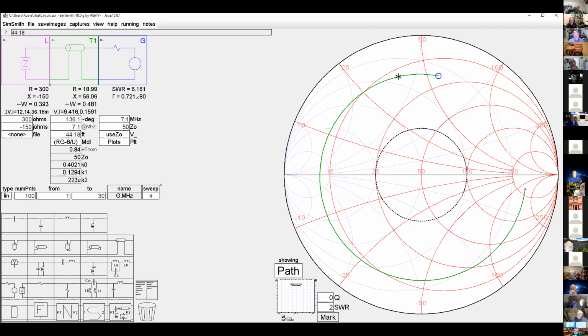So if I go from what I have, 40 feet in this case, to 45 feet, let's say I go to 50 feet, or close to it. Let me just do it this way. So if I go to 50 feet, now look at this. My R value is 56. My X value is 109. Now my transmatch, my matching box, may be able to handle 56 ohms. And all I had to do is add 10 feet of coax to this situation.